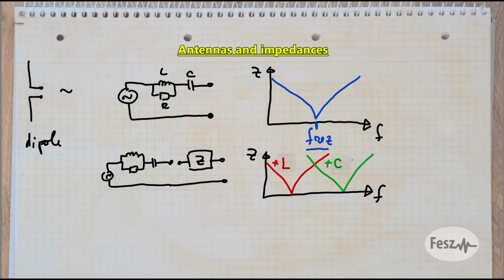So even if the antenna is too short or too long, it can still be made usable, but the important observation is that the point of minimum impedance, where we just see its resistance, is still just a point. You can resonate away the reactance only at a single frequency, using regular positive impedance components.